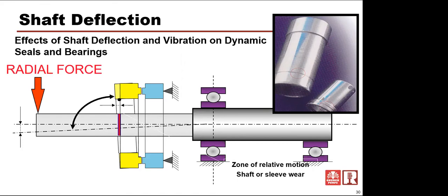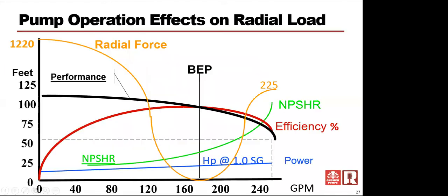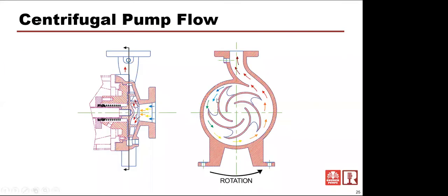And that's because all of that flow is trying to relieve itself from the high pressure side, where it can't go anywhere, back to the low pressure side. So it's going to force this shaft to move in and out in this direction as well, to try to get some of that high pressure fluid out on the fringes of this volute back across the front side of this face to the suction, which is the low pressure side.